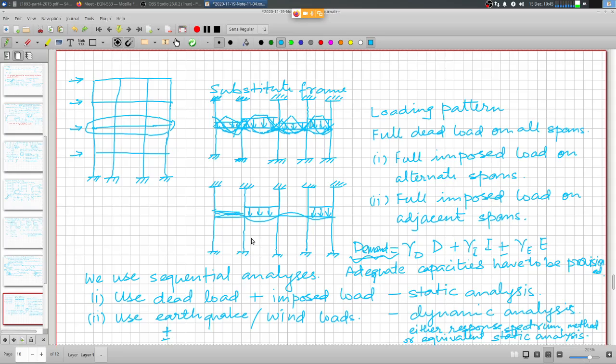Then you work on the particular section detailing, and you have the design, and finally you check up the drifts. After the preliminary design, you again go back and calculate the complete displacements and deformations and check the drift limitations. If the serviceability conditions are violated, then again you go back to the respective members affecting that particular parameter and revise the design suitably. So pretty simple, isn't it?